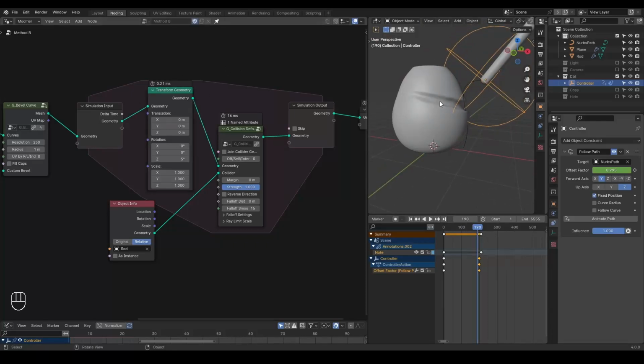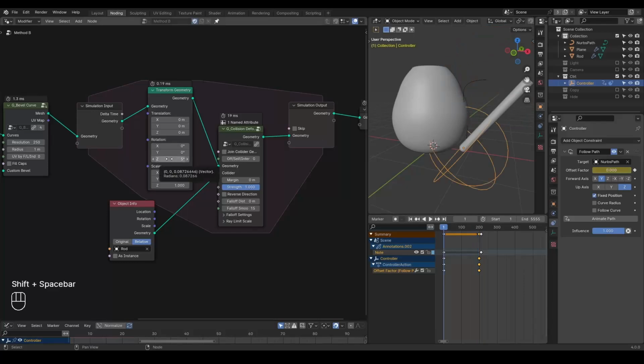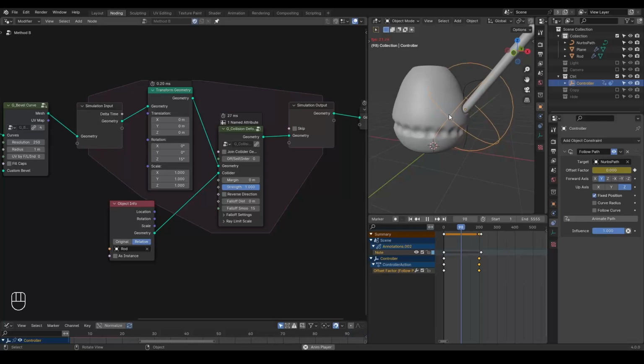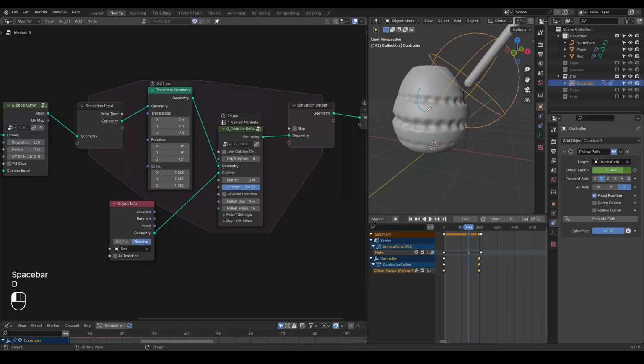So people may want to increase the step per frame. So I'm rotating 15 degrees. Then you will have these kinds of gaps, because we are rotating too fast, sometimes the collision is not being registered properly, and so on.